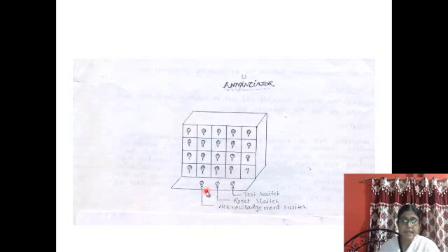The next step is the acknowledgement sequence. As I have just mentioned, after producing this visual and audio signal, the plant personnel will acknowledge the error. That means after pressing that particular switch, the audio signal will turn off and the corresponding lamp will remain glowing. That means the error is acknowledged by the plant.